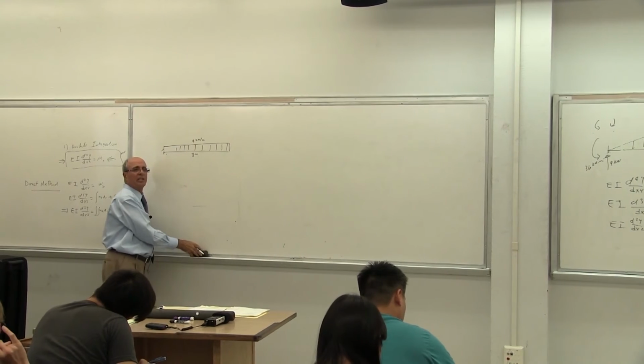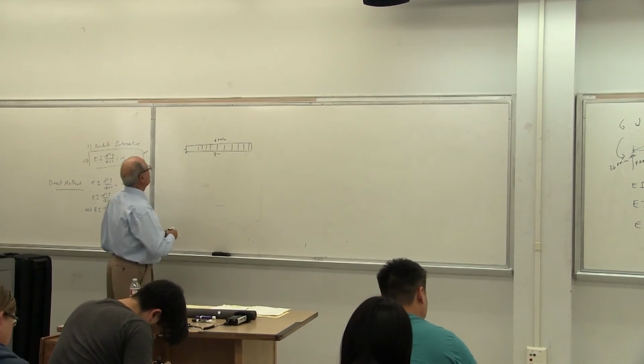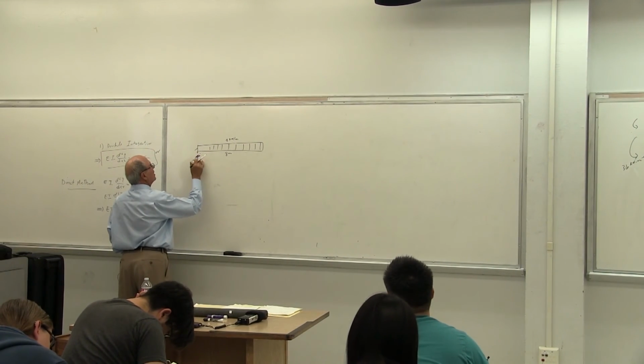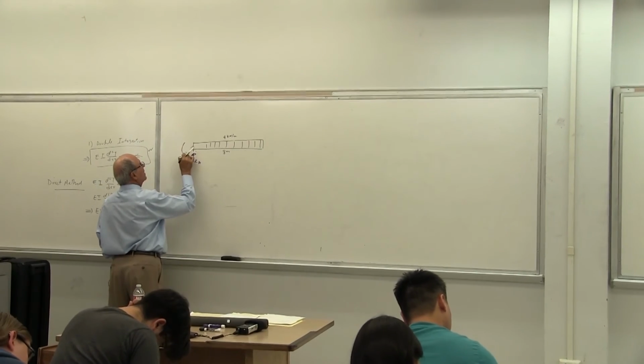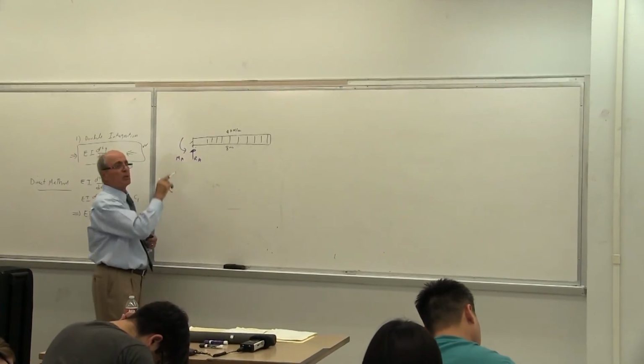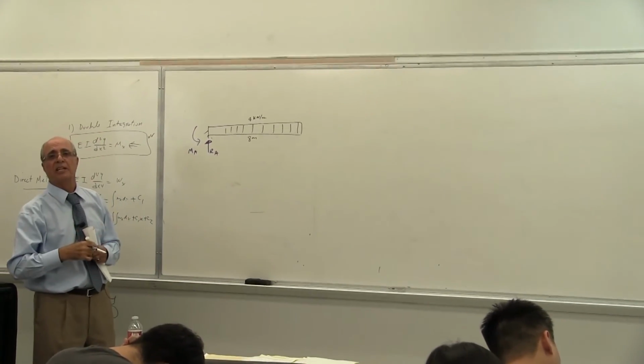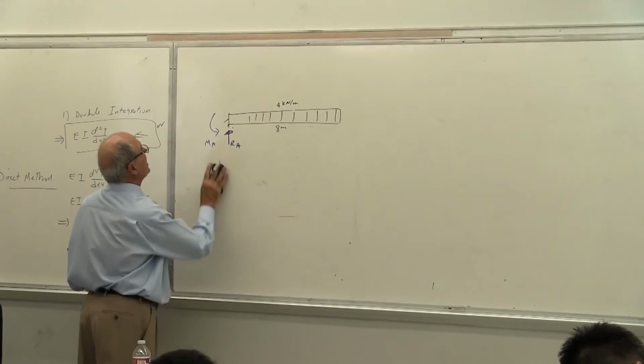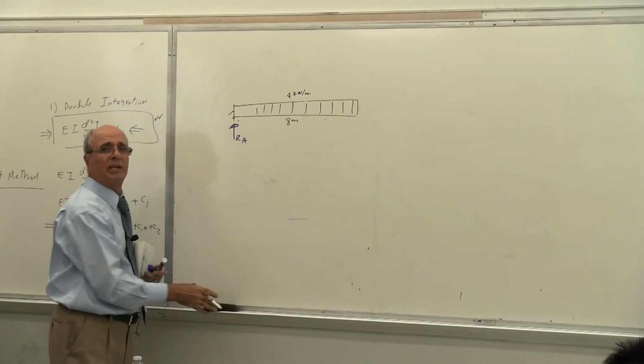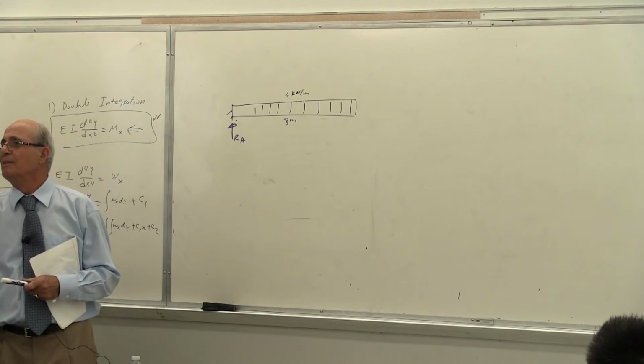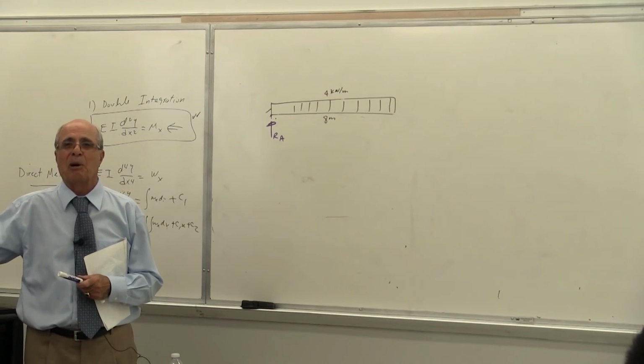I have reaction here, so let's put it this way. So here I have reaction RA and moment reaction MA. Don't forget, oh, this is another mistake. Some people forget about that. If you forget about that, you are back to a determinate problem, yes or no?